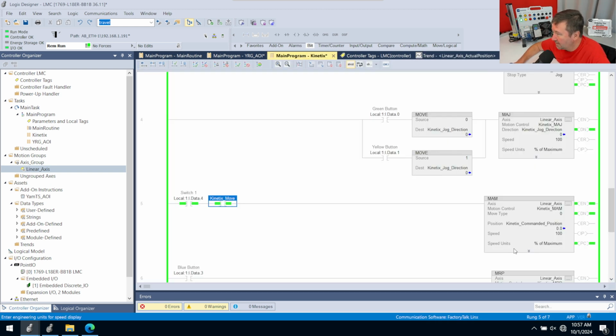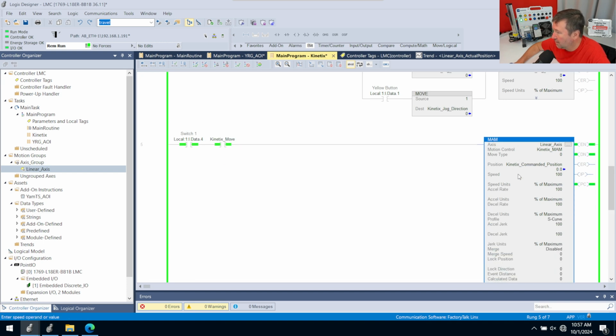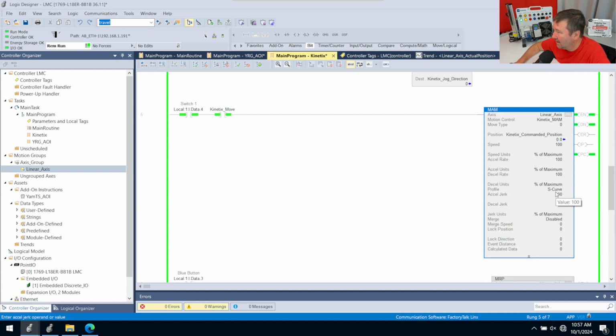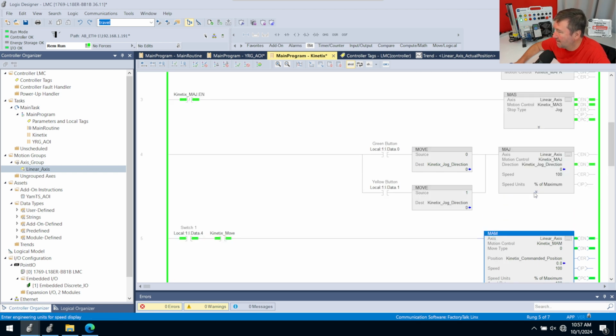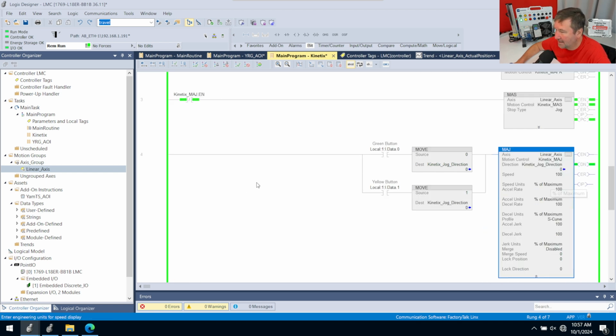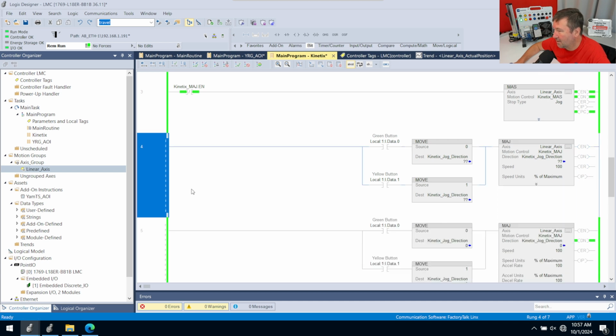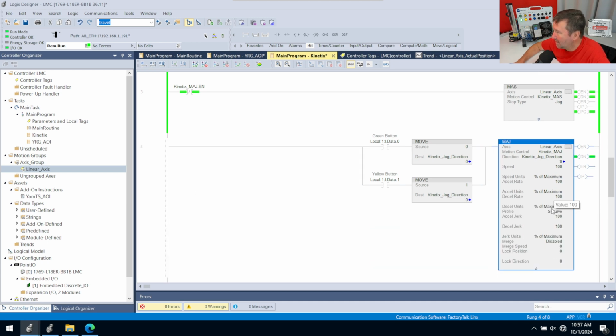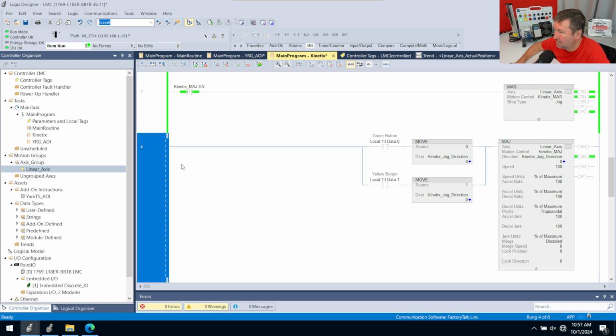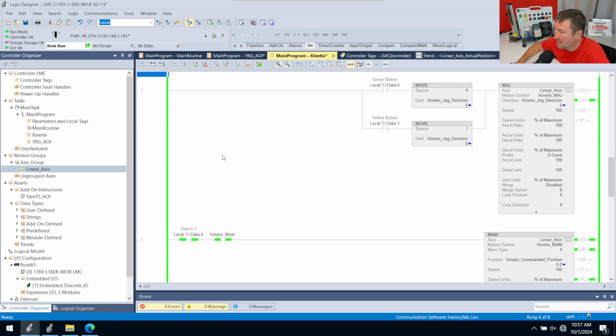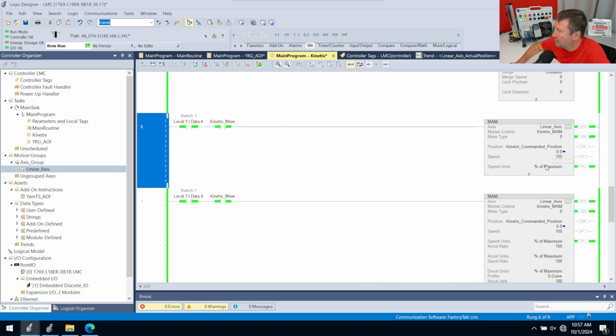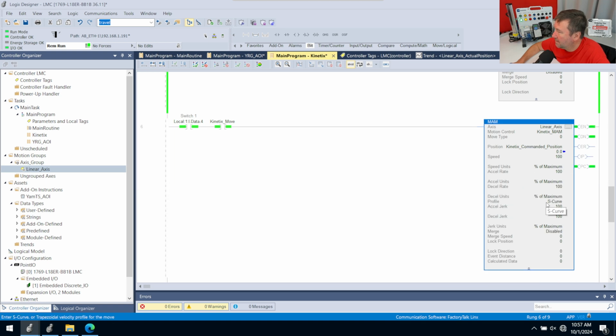So we go over here to our motion axis move, and we hit our arrow there under our hidden things. I selected S-curve right here, and I think I did the same thing. Did I do the same thing on our jog? I did. That was a total mistake on my part, I opened up that arrow. Instead of an S-curve, we want a trapezoidal move on our jog. We want a trapezoidal move on our MAM.